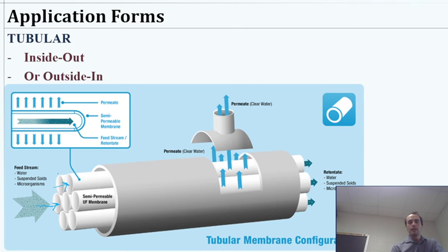So water could go into any of these columns or cylinders, and then we'd have a separation layer, and if it goes through one of these tubes, then it's collected in the wider chamber, and then will find its way out because it's pressurized and it just has to find a way out. And then we have the retentate over here. Again, the simple way to operate this is to apply some sort of valve over here to pressurize it and not let water go through easily, so it's forced to try to get out through the membrane, with just a little bit of the flow coming through here.